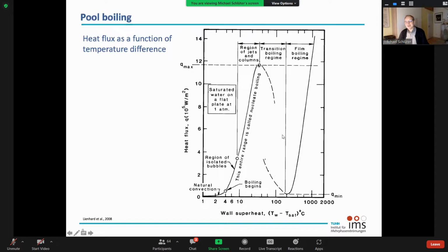But as you know, in nuclear power plants, this is not so easy, as you unfortunately have learned from the Chernobyl accident. So please be careful and keep away from this very dangerous and critical point, not to go to too high heat fluxes. And of course, this depends on the material system. So this is for water. If you have other materials, then you have to think about that and do some calculations again.